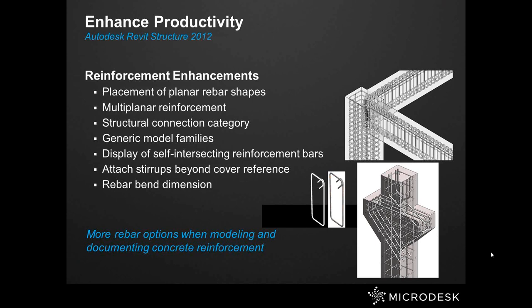Users have also the ability to model rebar shapes that are bent in more than one plane. In the Rebar Family Editor, users can create a copy of the existing shape connected via segments bent out of plane. This allows the creation of many of the most common multiplanar shapes.